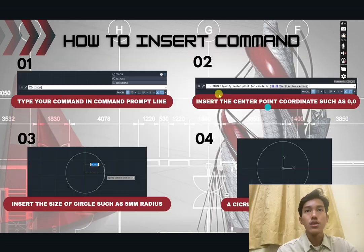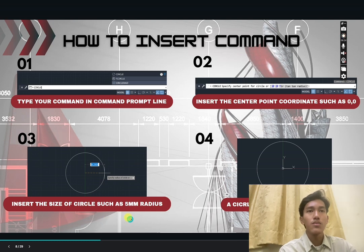Okay, how to insert a command? Firstly, you must type your command in the command prompt line, such as circle. Insert the center point coordinate such as 0,0. Then insert the size of the circle, such as 5 mm radius. A circle with 5 mm radius is drawn like this.